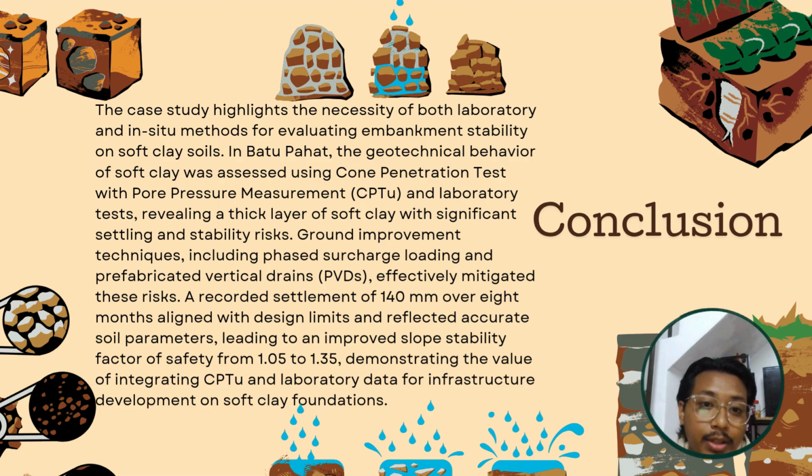For the conclusion, the case study highlights the necessity of both laboratory and in situ methods for evaluating embankment stability on soft clay soils. In Batu Pahat, the geotechnical behavior of soft clay was assessed using cone penetration tests with pore pressure measurements (CPTU) and laboratory testing, revealing a thick layer of soft clay with significant settlement and stability risk. Ground improvement techniques, including surcharge loading and prefabricated vertical drains, effectively mitigated this risk.